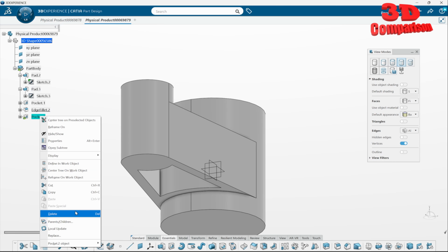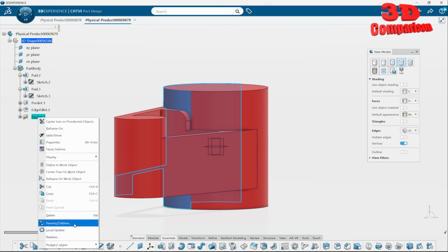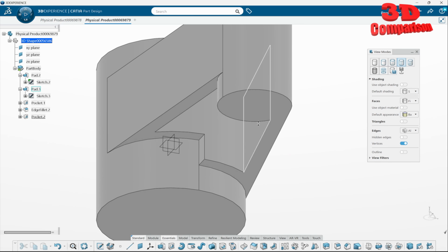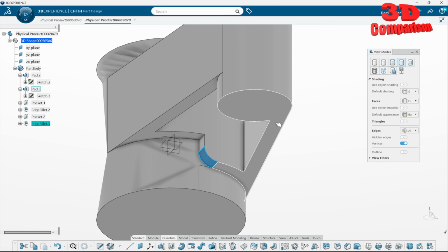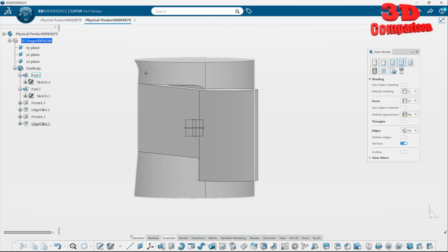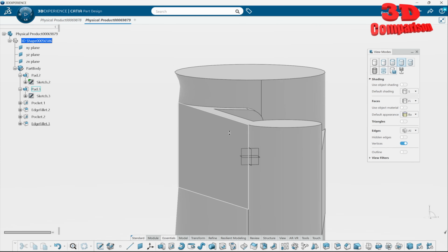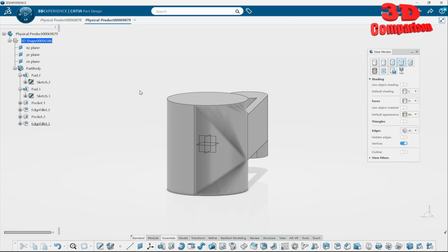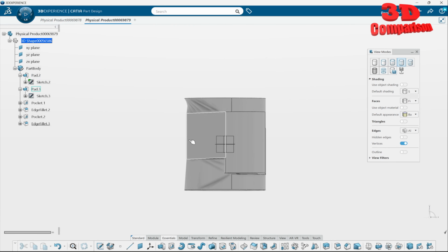But if I set this also to be within the work object, we're going to have an update error over here. And if I update this locally, it will still work. So we still have that seam in the middle, and now if I apply this edge over here, this will work, but again we have those problems with the surface, as we can see over here. This is no longer a surface that is part design. It's oddly shaped, and I'm really curious, if I export this as a STEP file, what exactly will be the output, because clearly the mesh has some problems.